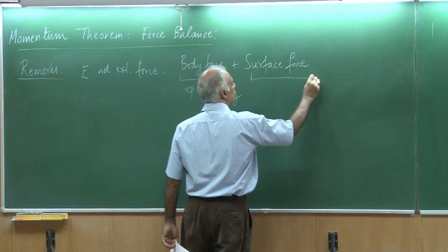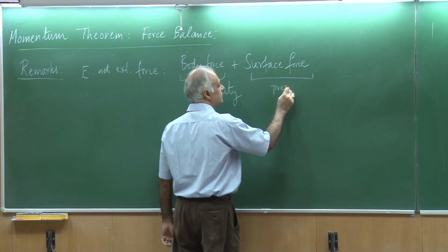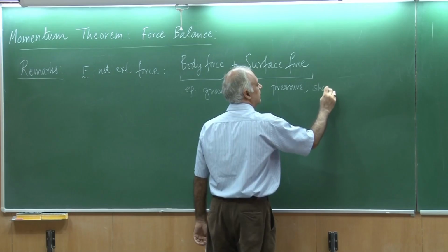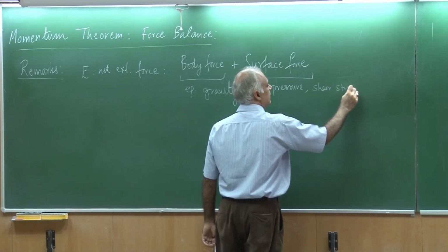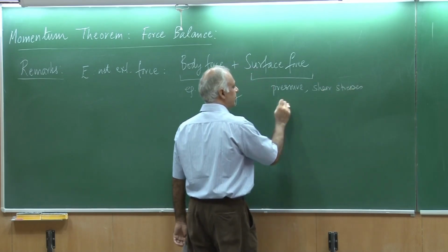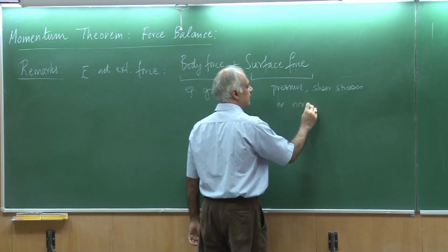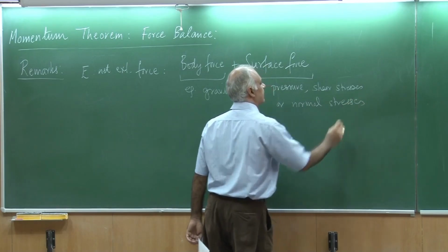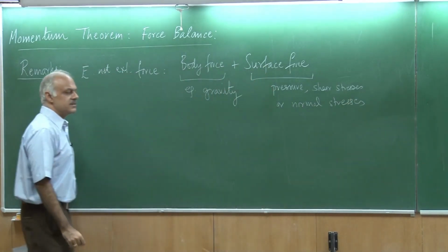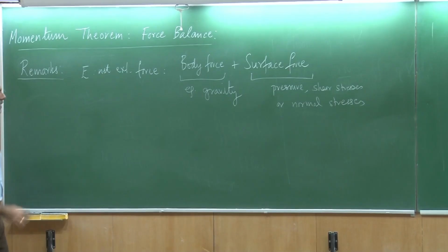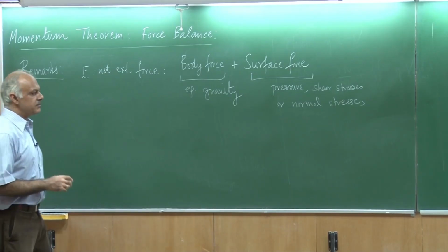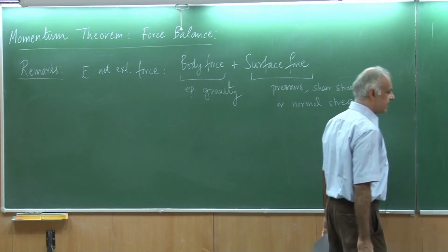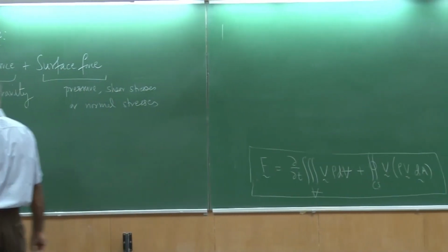Examples of surface force would be because of the pressure, or for example the shear stresses, or maybe the normal stresses. So the stress in general. They would constitute surface forces. We need to account for all of them when we talk about the F on the left hand side. So that's remark number 1.